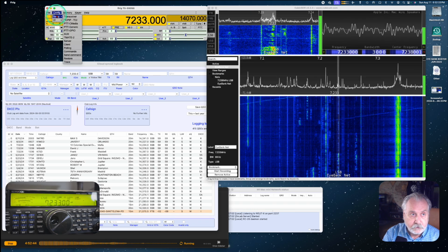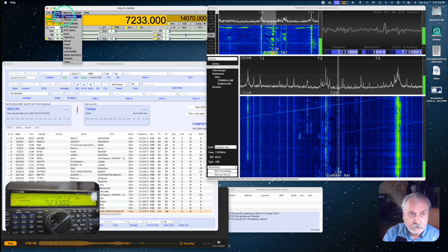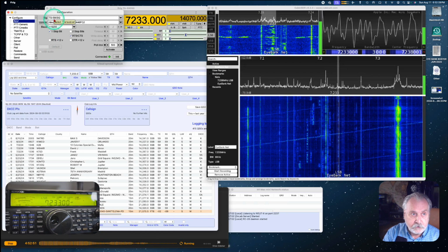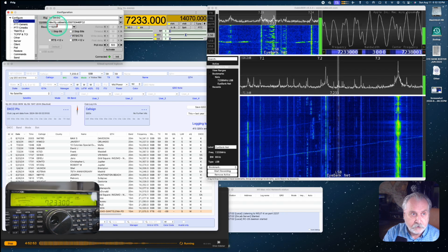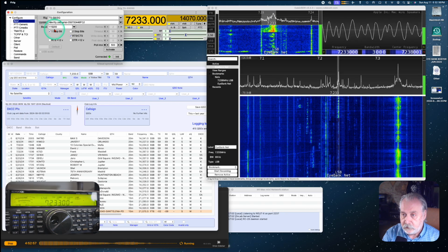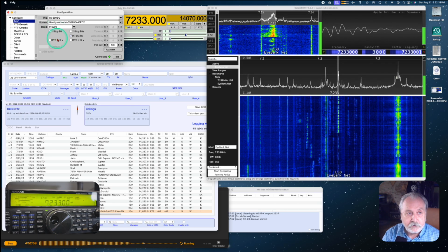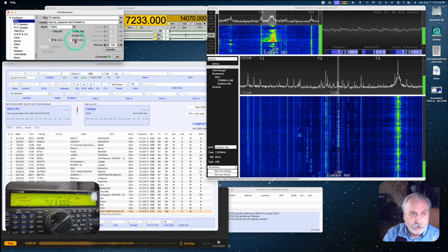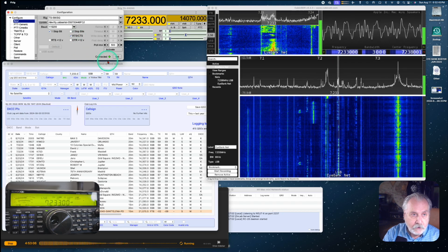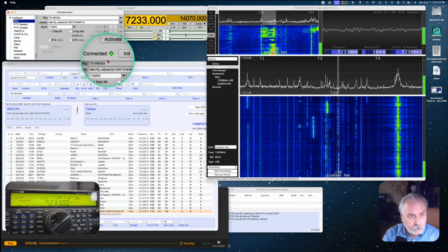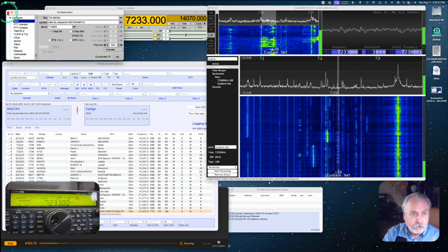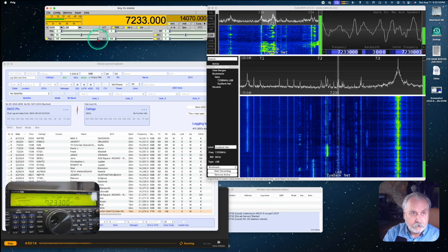Then I also showed you in the setup config for the transceiver here, I've got the TS-590SG as the rig selected, that same port selected. Got my baud rate, which is 115.2, which has to match what you've got set in your radio. One stop bit and RTS, CTS checked. Okay. And here I've got the green light showing it's connected on my init.